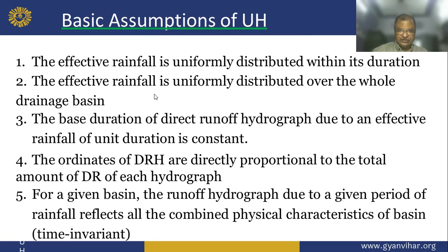The base duration of the direct runoff hydrograph due to an effective rainfall of unit duration is constant, and the ordinates of the DRH are directly proportional to the amount of direct runoff.